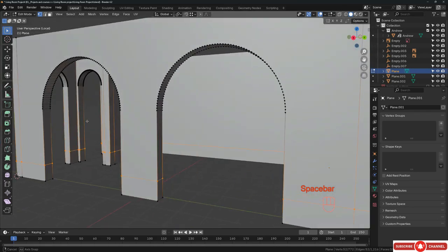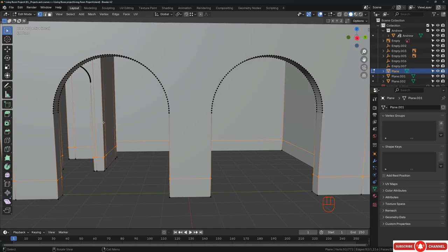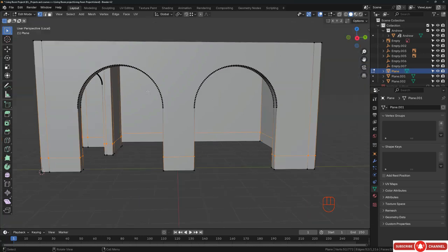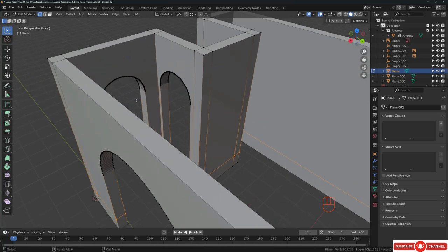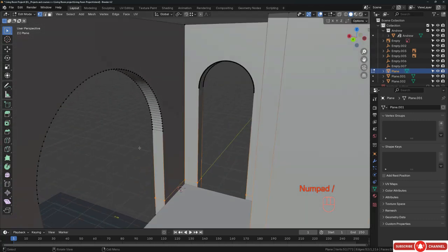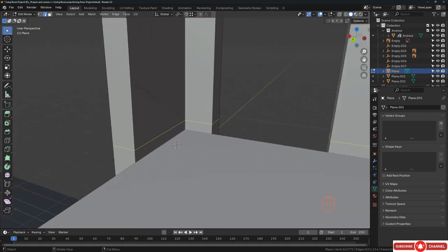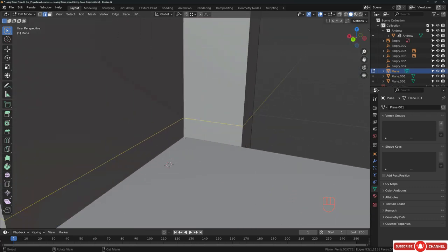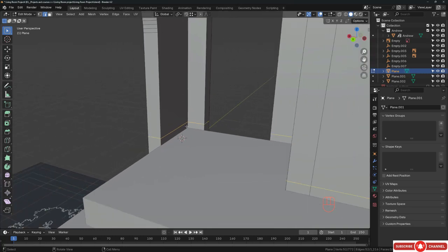I will create another cut like that. All right, it's working. So if that happens, just create another line and another level, and I think that will help to avoid this problem. Anyway, after creating this edge, you can go to the edge selection mode and determine the height. So this edge should reach the ground, as you can see right here, the next level, this one.